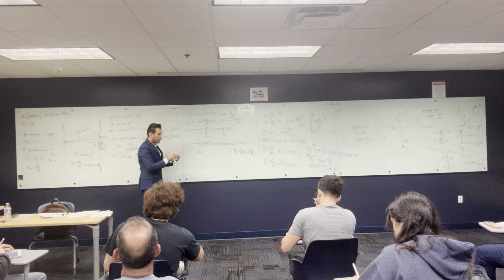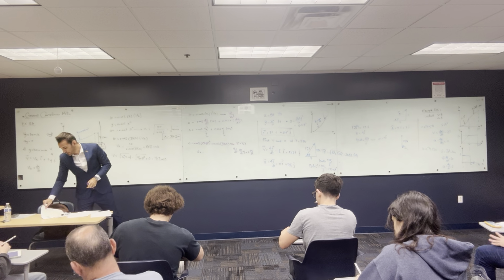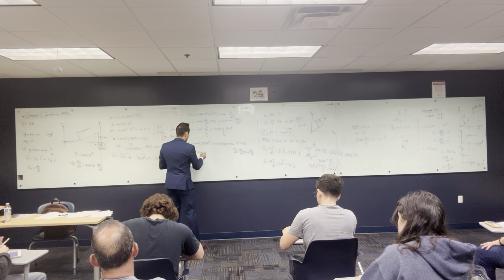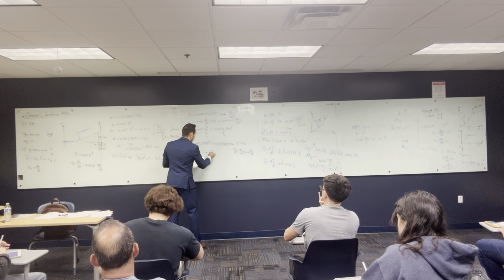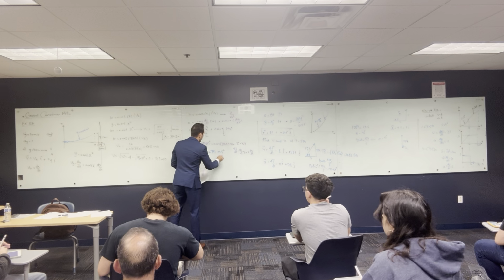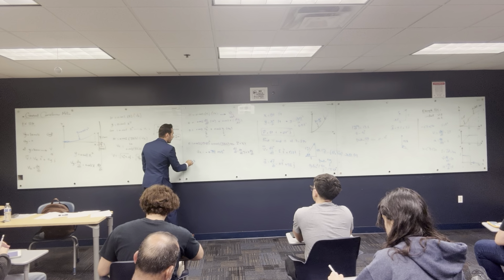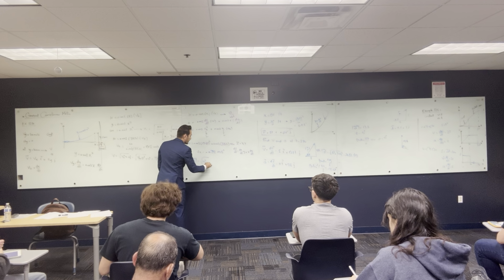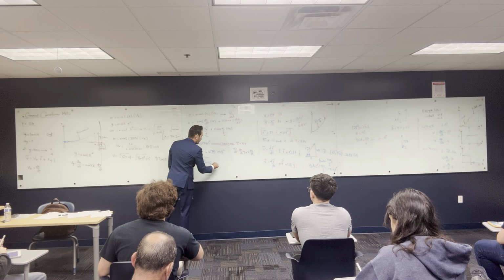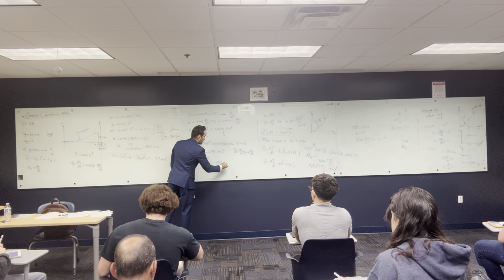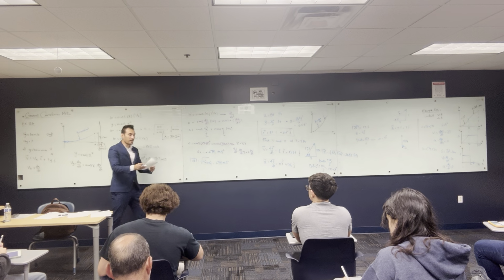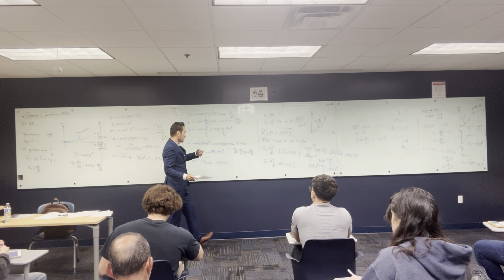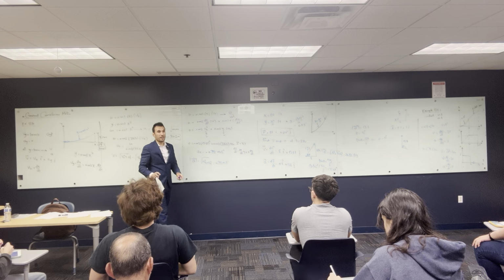You're going to send this to the other side, and you will find out that Ax is equal to negative 0.791 meter per second squared. So the magnitude of A is going to be equal to the square root of Ax squared plus Ay squared, and this is going to give you 0.791 meter per second squared. And definitely the magnitude is positive because you are taking the square root of the square of the negative value, which is going to be positive. Does anybody have any question on that?